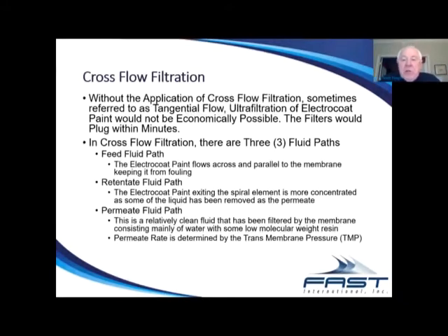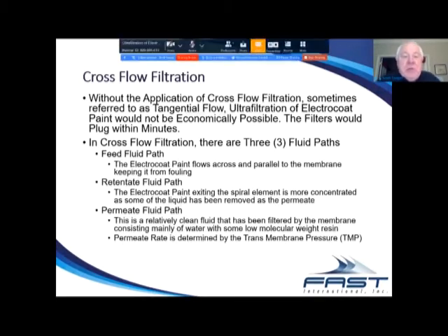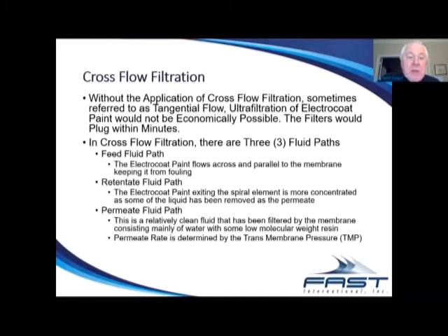Without the application of cross-flow filtration, sometimes also called tangential flow, so you have TFF and CFF filtration, the ultrafiltration of E-coat paint would not be economically feasible. In fact, the filters would be plugged within minutes, if not seconds. In cross-flow filtration, there are three phases to the fluid path. The feed fluid path, which is the electrical paint that comes into the element, flows across the membrane, and that flowing across the membrane keeps the membrane from fouling. Therefore, it lasts more than minutes, in fact, years.